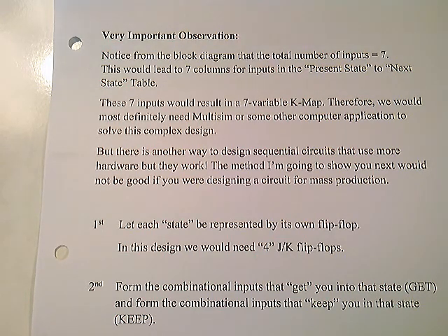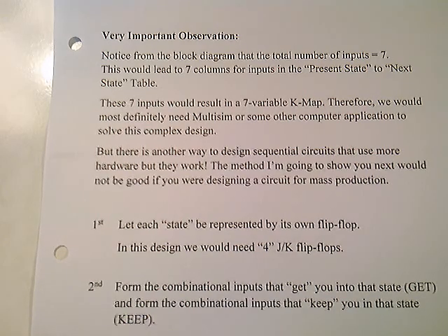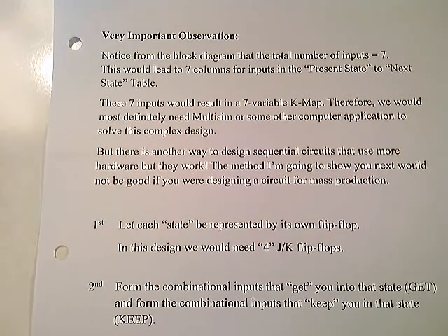Now, I've used this technique as a digital design engineer at Texas Instruments when we were designing simulators for the F-14 fighter back in 1975. I was responsible for the I/O unit of that mini computer in that simulator, and I actually used this technique. First, let each state be represented by its own flip-flop. In this design, we would just need 4 JK flip-flops. We couldn't get away with just using 2.